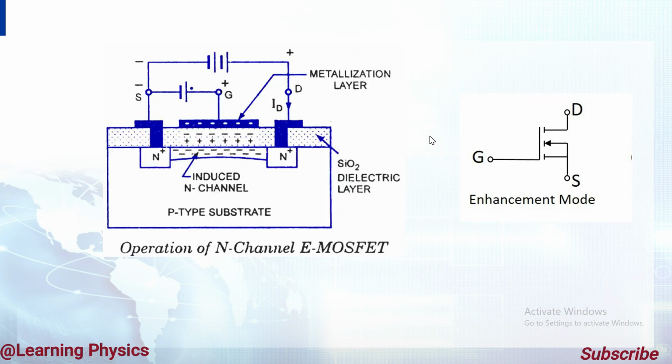And here is another form of transistor, the E-MOSFET or enhancement type MOSFET, in which channel material is physically absent or not present, and the charge carriers virtually make the channel due to the biasing applied from source to drain and gate to source, and it is also controlled by the VGS gate to source terminals.